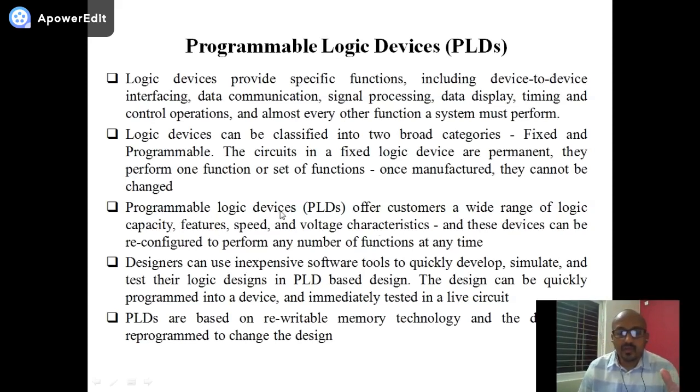So the programmable logic devices offer customers a wide range of logic capacity. You can reprogram or reconfigure the FPGA and CPLD every time for making prototypes of different circuits. Designers can use inexpensive software tools, for example Xilinx Project Navigator, which we have used, to quickly develop and simulate, and then send the logic design to the fab for fabrication.